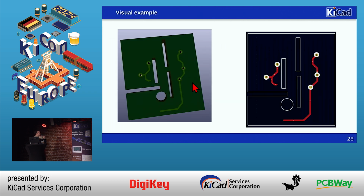A more visual example now. So I have this board, which does pretty much nothing, just a test case. I want to know what the shortest path is between net A and net B. So first of all, we build the network for the board features. Then we add the connection from the nets to the board features node, basically. And then we run the shortest path algorithm, which in this case is this one.